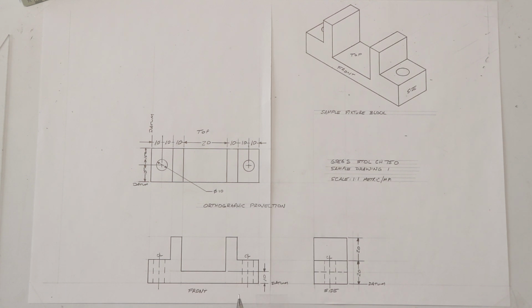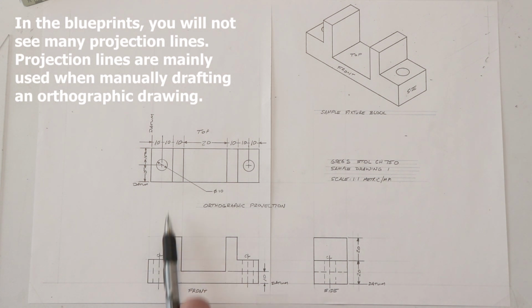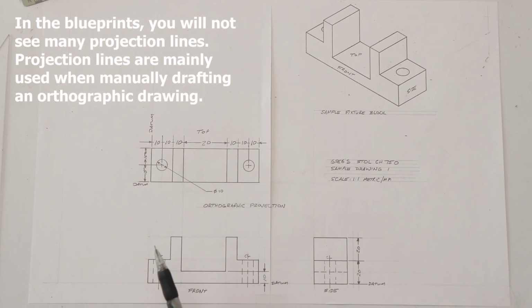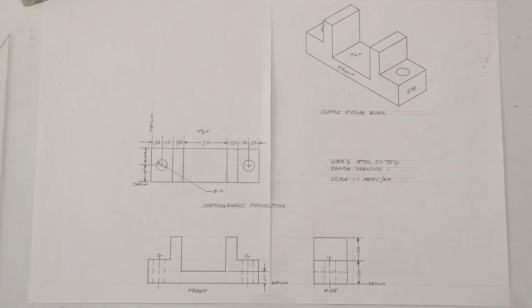Normally you don't see a lot of measurement and datum lines that reference themselves off of hidden feature lines. Most of your measurement lines are going to go up to a solid line that is part of the visual plane that you're looking at. Moving up, again, we have a series of very faint lines up here. These are projection lines going up to where the top view of the part is. That's why this is called orthographic projection. We are projecting the views in different planes so that you can see where the relevant information is.